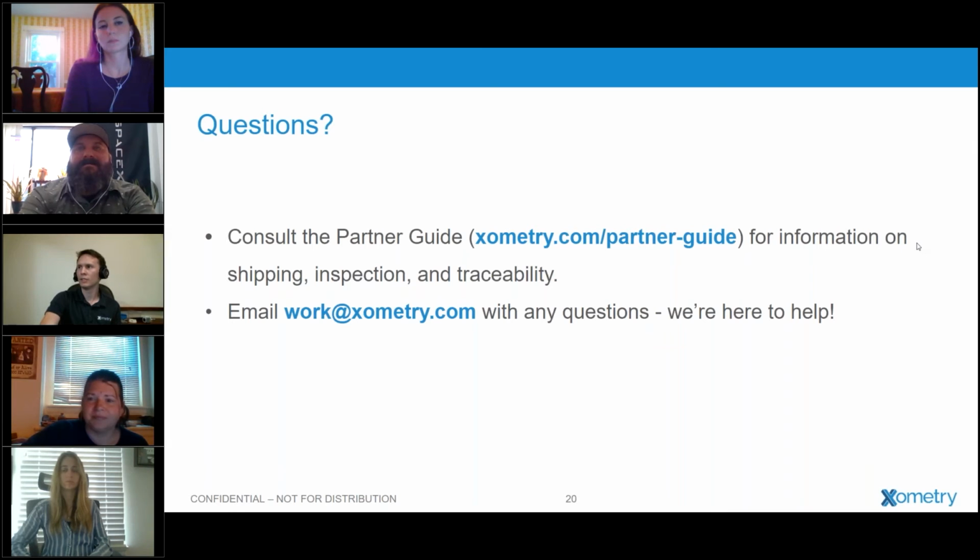Yeah, and I just want to note that the standard inspection plans that we have have a 100% pass requirement, right? So if you're measuring only the good ones and ones are not passing, it's not hitting the standard inspection as it is. Having those measurements there is important, but obviously you're going to be measuring to your standard sampling plan with the understanding that if something is out of spec, it's a reject. So we want to make sure that we elevate and escalate that as required.